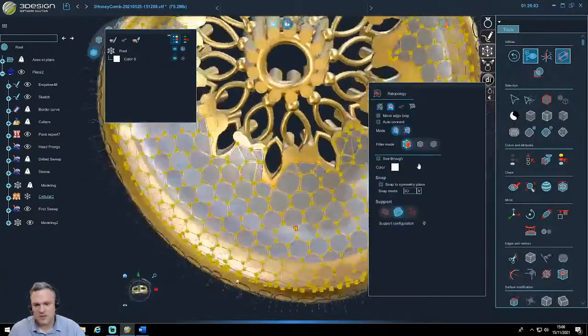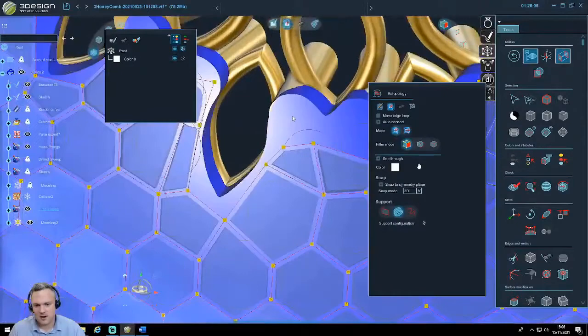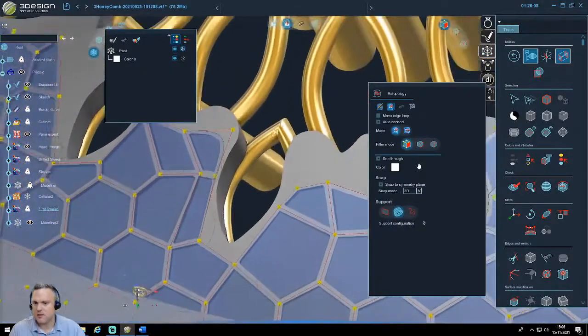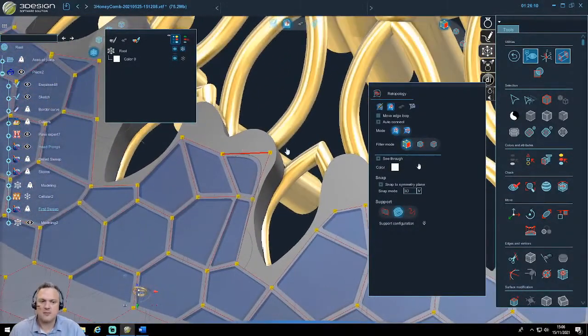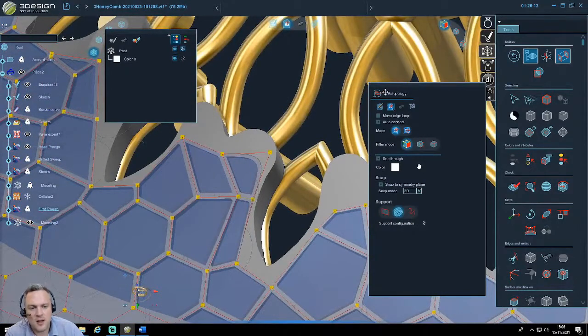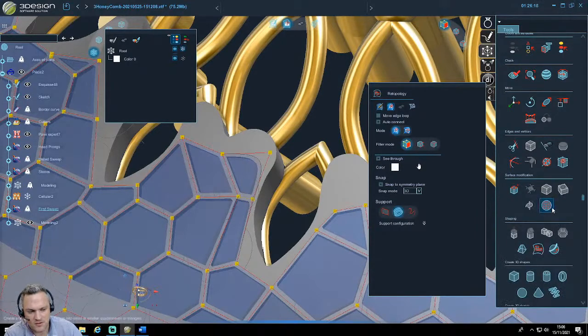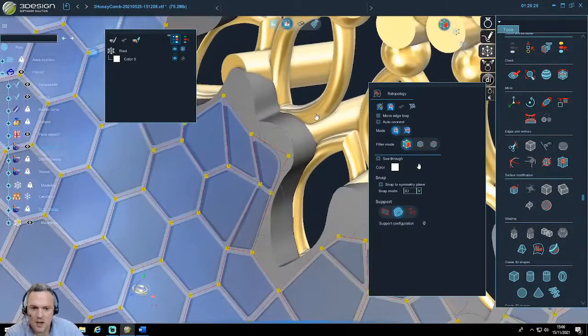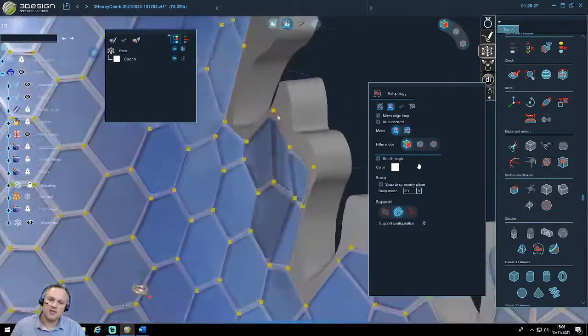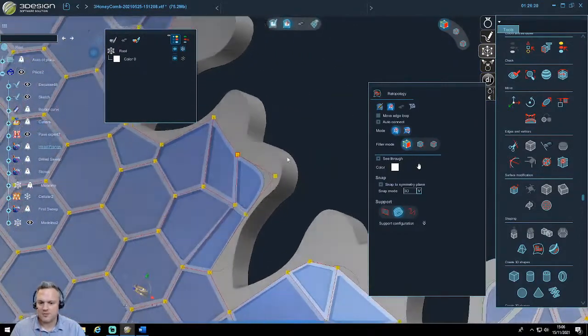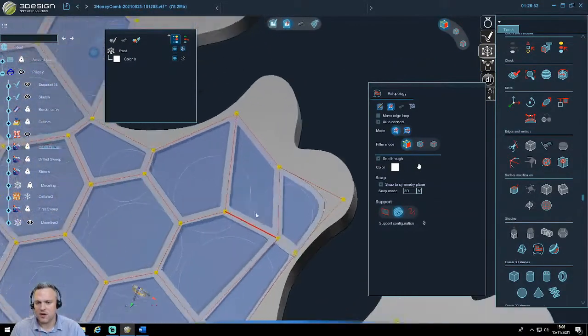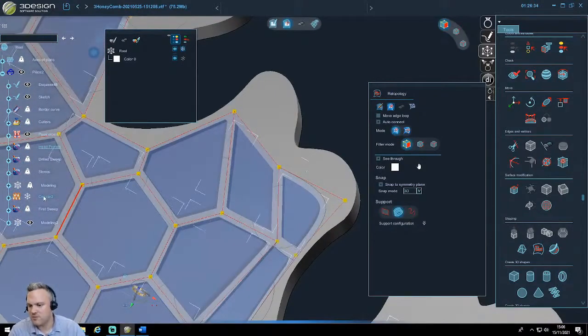So you can see that now each object is transformed into surface, and I can modify the surfaces again with the same option I used this morning for the creation of the seahorse, the retopology. Retopology allows me to work directly on a 3D object, which is currently the object you have in gray. And you now have the possibility to modify the created points from the automatic honeycomb, and I can change them manually.